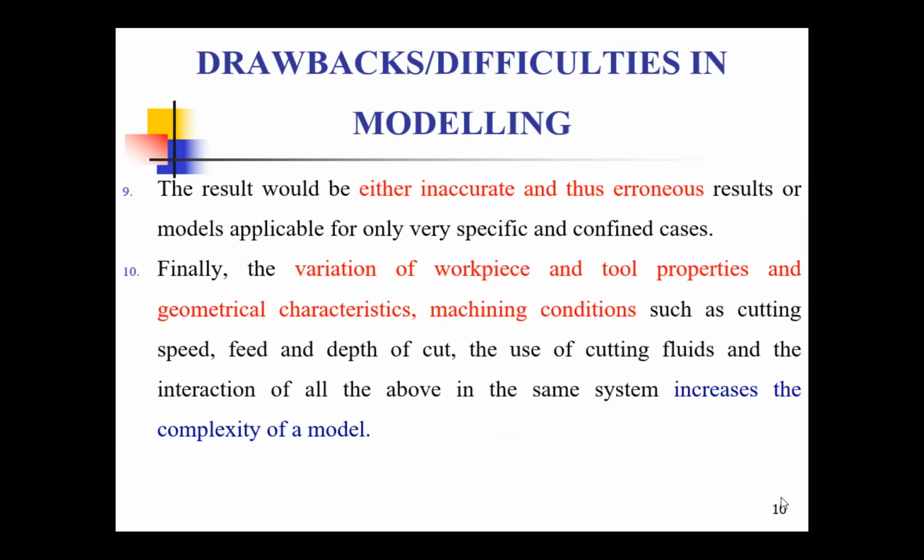Apart from this, there is the variation of tool and workpiece properties and geometric characteristics, the machining conditions, and the usage of cutting fluids. The cutting fluids may be provided as cryogenic cutting fluid, liquid nitrogen or carbon dioxide, or I can supply flood cooling, or we can do dry machining, or minimum quantity of lubrication, which we call MQL.